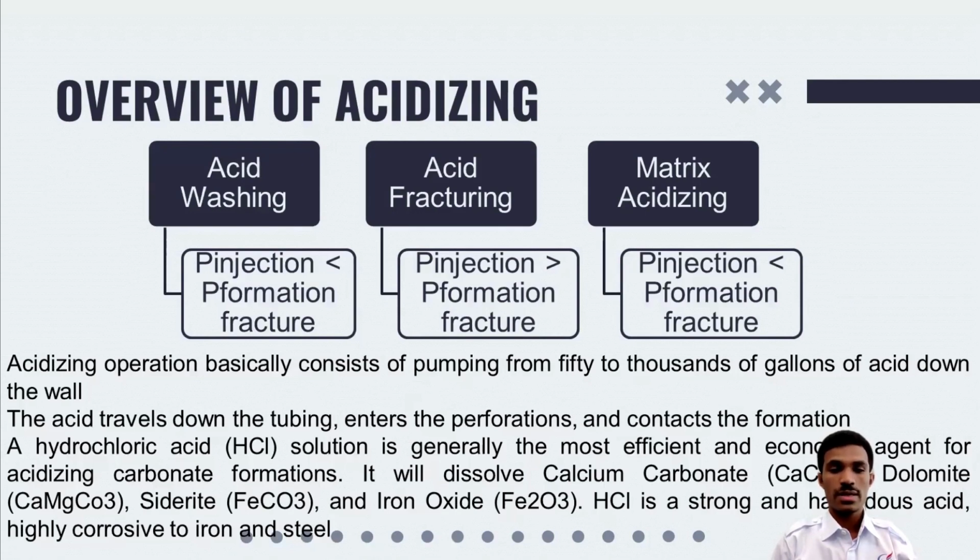Hello, I am Yuliana Citrayan. The next presentation will be handled by me. There are three general categories of acid treatment: acid washing, acid fracturing, and matrix acidizing. In acid washing, the objective is simply tubular and wellbore cleaning. Treatment of the formation is not intended. Acid washing is most commonly performed with hydrochloric acid (HCl) mixed to clean out scale, such as calcium carbonate, rust, and other debris restricting flow in the well.